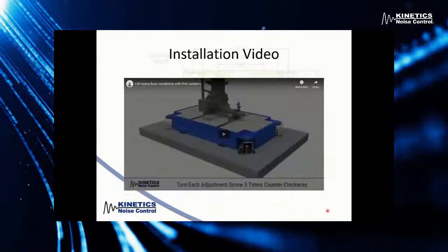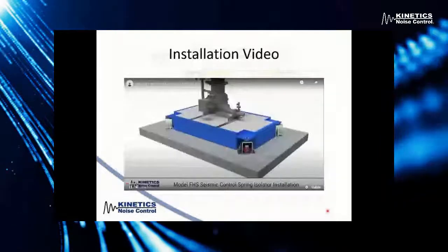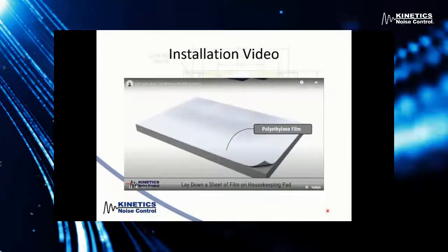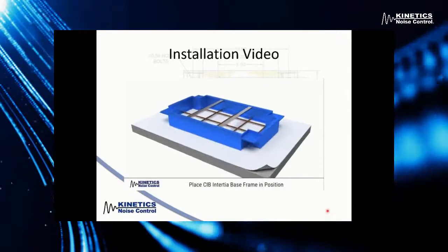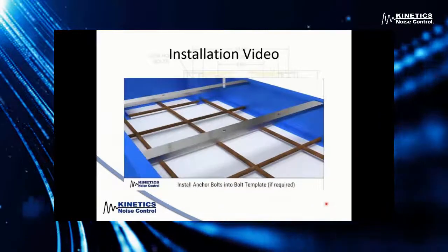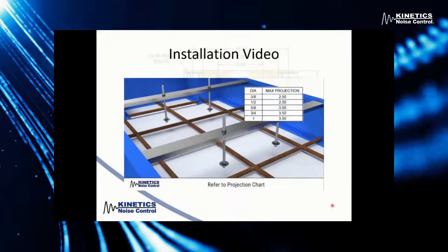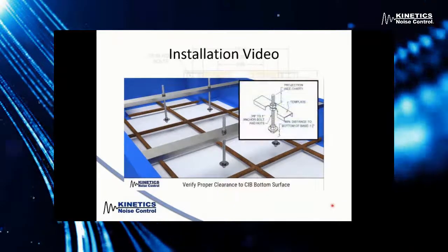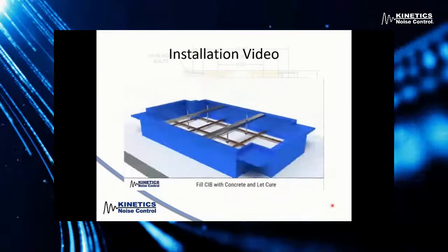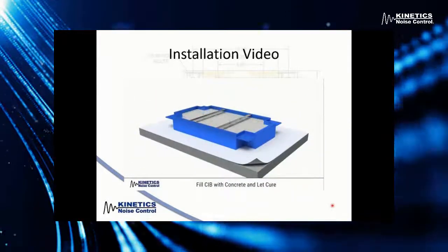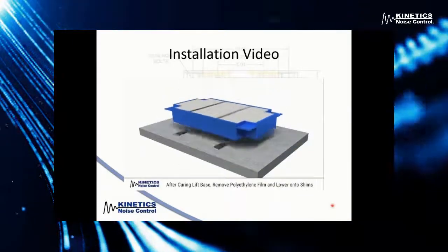We also have the same thing available for our concrete inertia bases. So anyone on site who is unfamiliar with the product can scan their cell phone over the QR code, and it's going to launch the YouTube video right on their phone or tablet. This one's showing some predetermined threads there for the pump to mount to, and then you're going to fill the base with concrete, and then the same kind of concept with adjusting the isolators correctly. All of these videos are available on the Kinetics website, as well as the QR codes that come on the product.